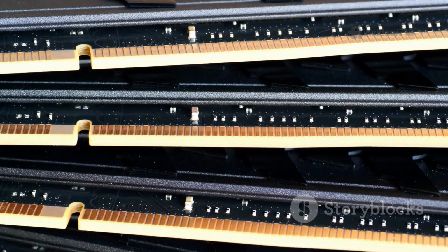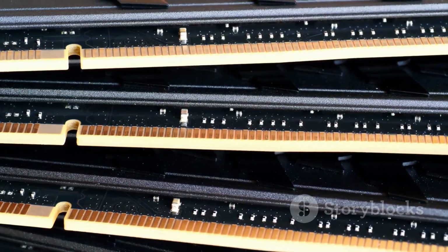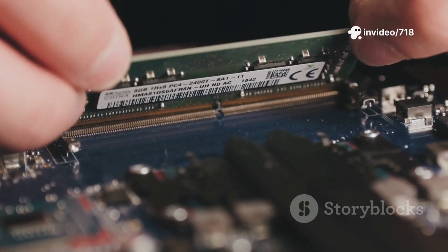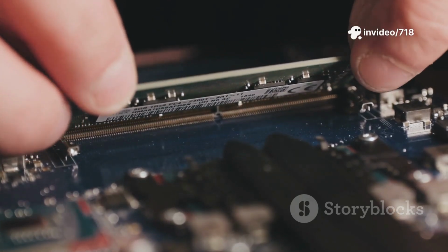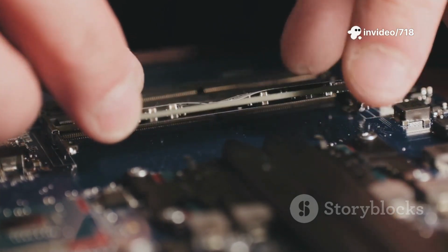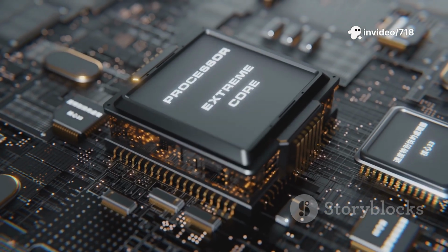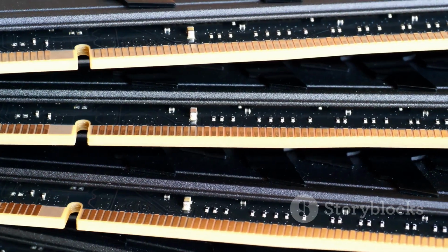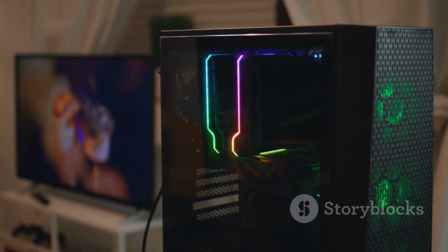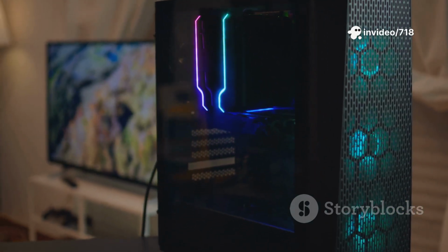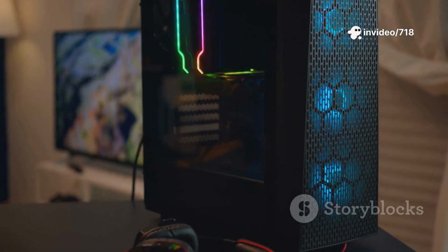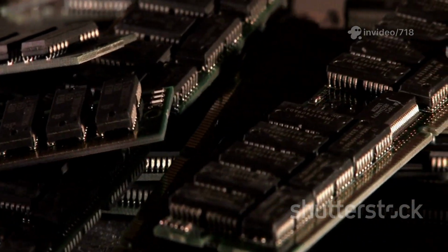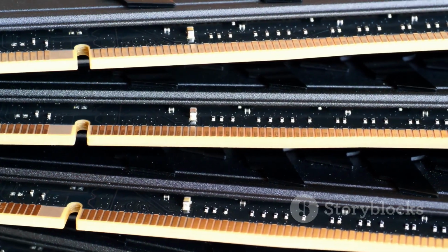The next big leap was double data rate SDRAM, or DDR SDRAM, which appeared in the late 1990s. As its name suggests, DDR technology was able to transfer data on both the rising and falling edges of the clock signal, effectively doubling the data transfer rate without increasing the clock frequency. This was a massive boost in bandwidth, providing the much-needed memory performance for increasingly demanding applications like 3D gaming and multimedia processing.